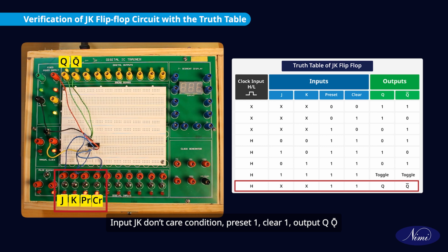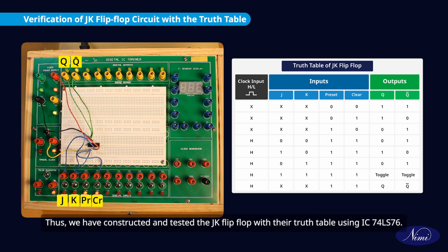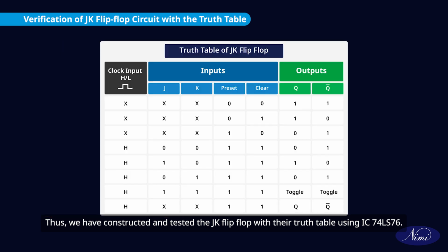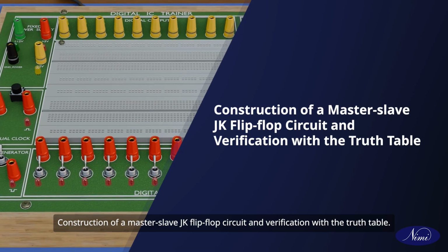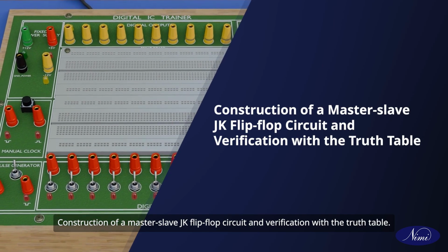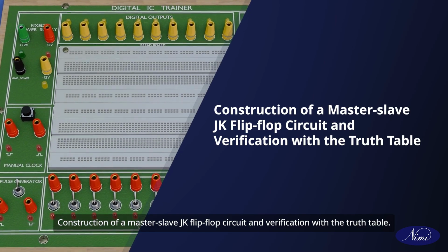Input JK don't care condition, preset 1, clear 1, clock pulse high, output Q Q bar. Thus, we have constructed and tested the JK flip-flop with their truth table using IC74LS76. Construction of a master-slave JK flip-flop circuit and verification with the truth table.